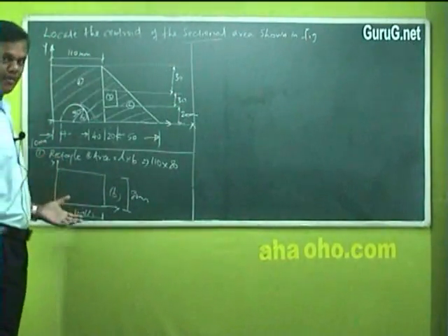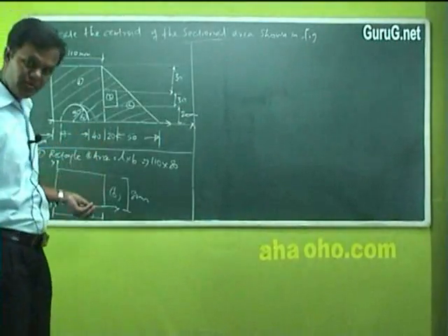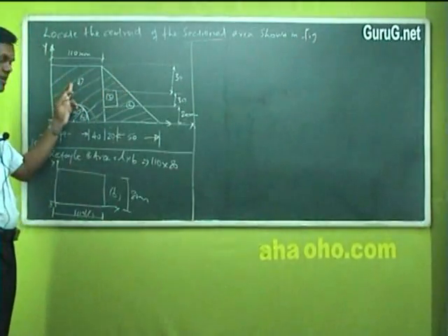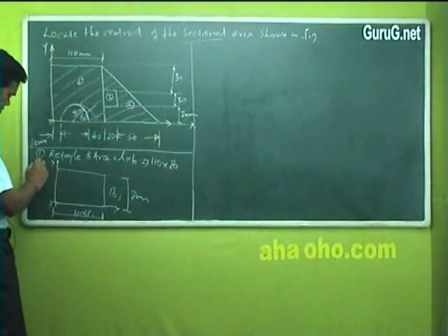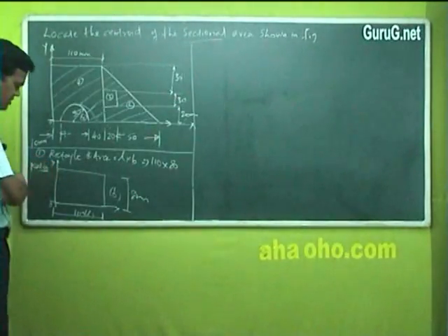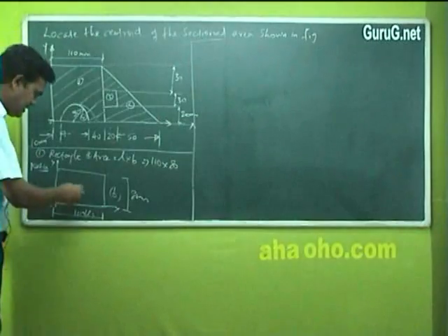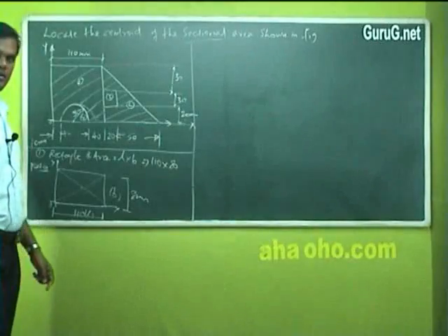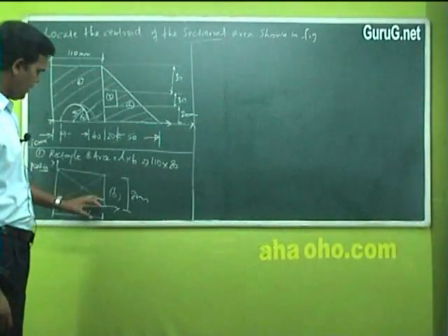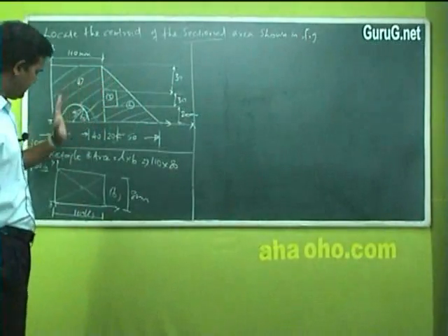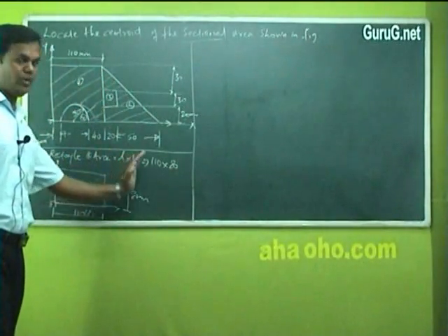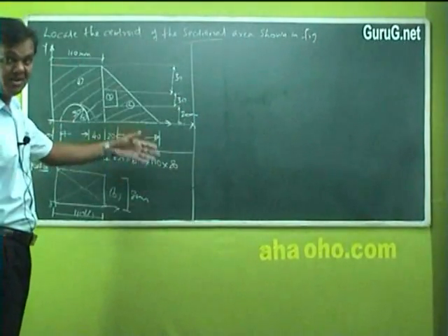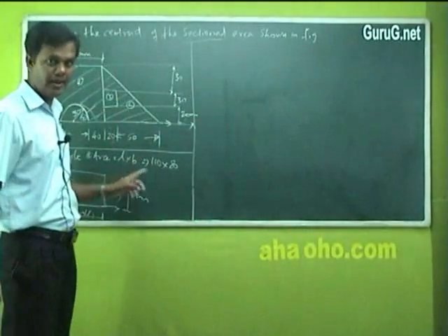Now we are finding the individual center of gravity. There are 4 different shapes grouped together. I am finding for portion number 1, the first portion, a rectangle. CG for this one, how do we find out? Just make a cross diagonal mark, and using the formulas, the shape is given, x value and y value I have already told you. There are 15 to 16 sketches in the book which you have to remember. It is mandatory for you to remember. Only then you can solve any question.